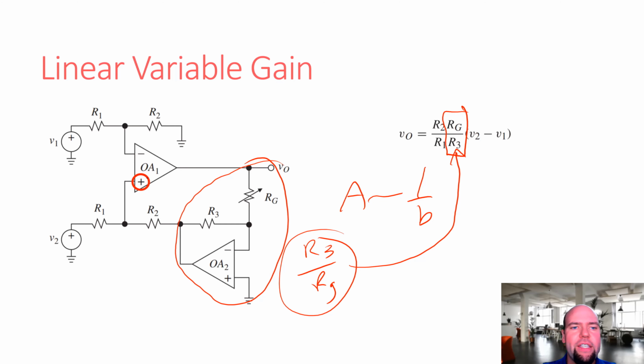Another thing to note is, why is our feedback connected to the positive terminal now? So think about it. Why? This normally kills an op amp. You can't have feedback to the positive terminal. That's going to result in unstable operation. So why are we doing it here? Because this was an inverting op amp. So what we're doing is we're taking the output and inverting it.